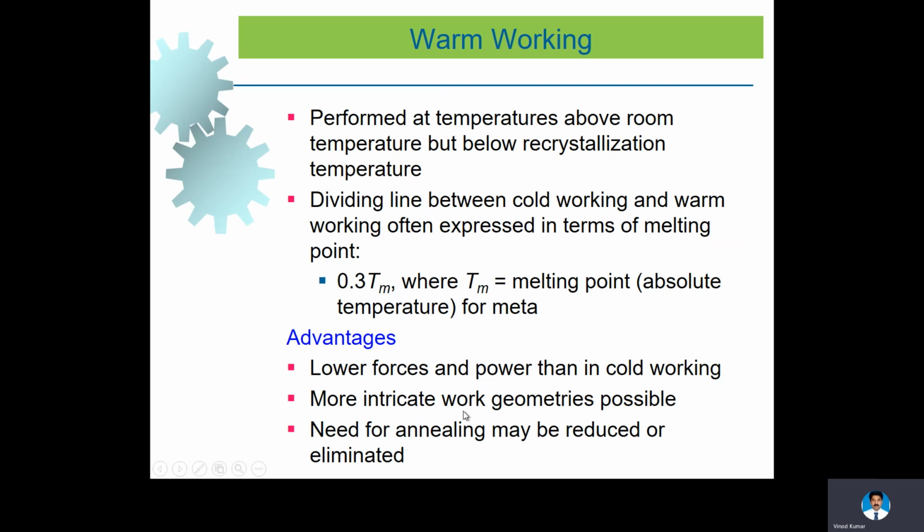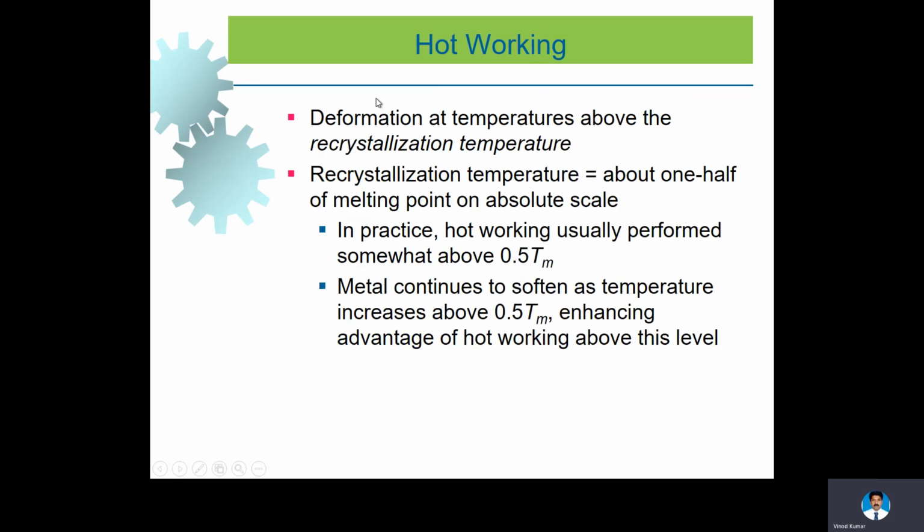Cold working needs annealing to reduce or eliminate strain hardening. Here, compared with cold working, the annealing process can be eliminated using the warm working process. Now we have the hot working process, which is deformation at a temperature above the recrystallization temperature.